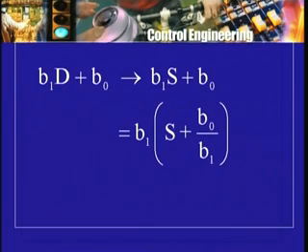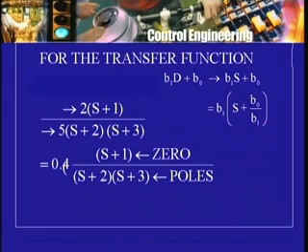So, I may get a non-unity coefficient multiplying, therefore I have to write it. If it was 1, I can suppress it. If it is not 1, I have to write it, like 0.4. And so, this can appear on the pole zero diagram, or I can put a statement saying that this coefficient will be 0.4 or whatever it is. So, the transfer function information can be shown as a pole zero diagram, and we will see that this diagrammatic representation is going to be useful as we proceed further.